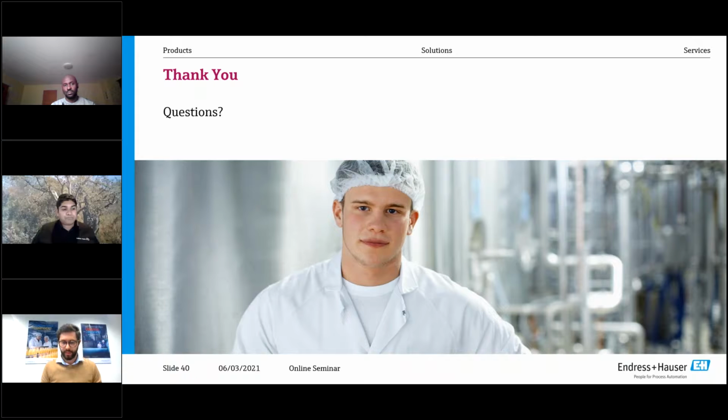Excellent. Just one comment on that. We do have some customers using the Trust Sense in the food and beverage industry, using the Trust Sense feature to reduce their calibration time. Whenever they need to do any calibration, they quickly remove the sensor from the process and put it in the thermal bath, and it goes up to 118 degrees. Once it reaches 118 degrees, it self-calibrates, and the customer just takes it back to the process, so they can reduce the amount of time during calibration as well.